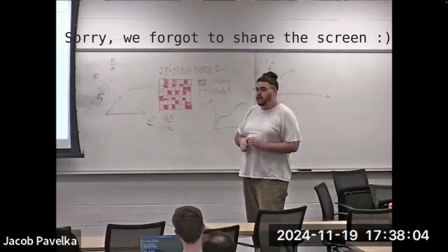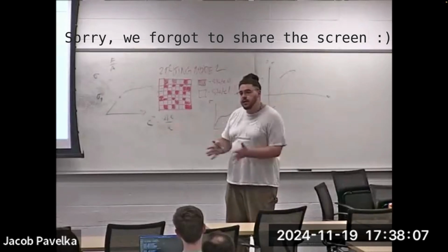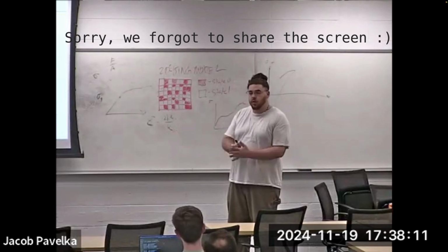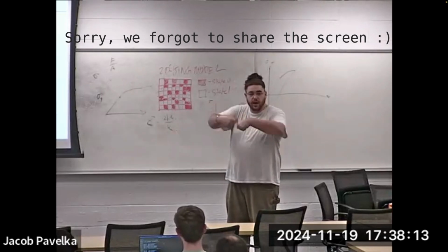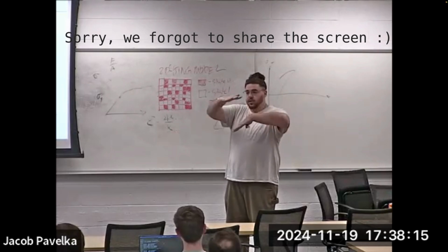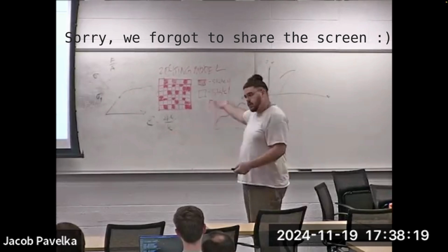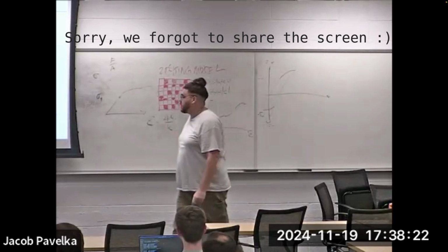So kinematic hardening is going to be really important if you have some cyclic problem where the part is going into tension and then compression over and over again. Or say you have a wire that you're bending like this and this. One side is going to be in compression and tension, and then the reverse, you go back and forth. And you need kinematic hardening for these kinds of things.